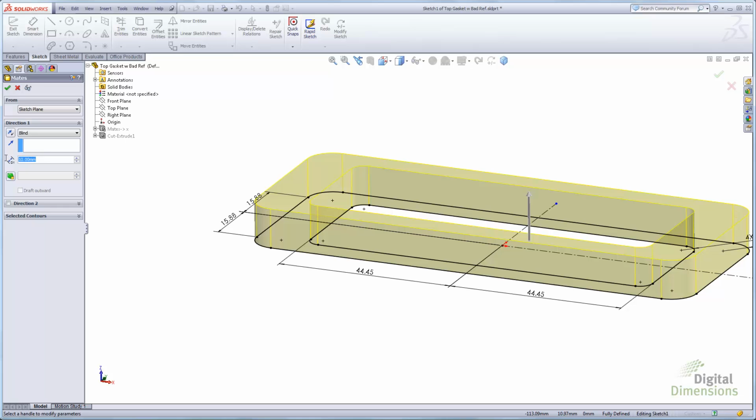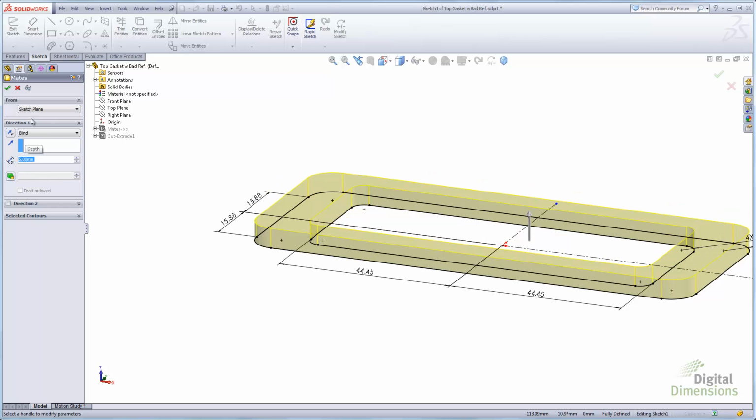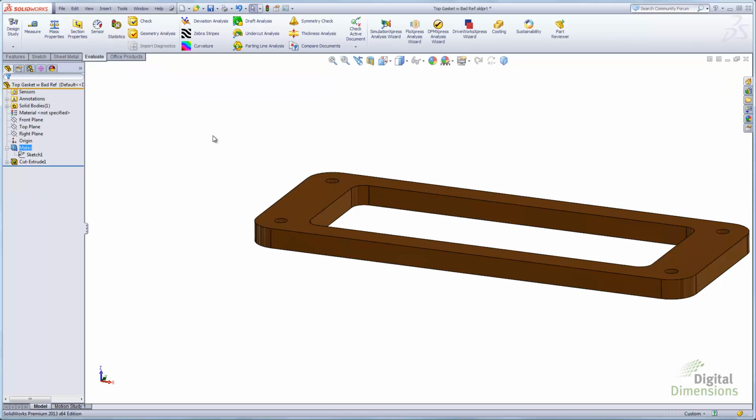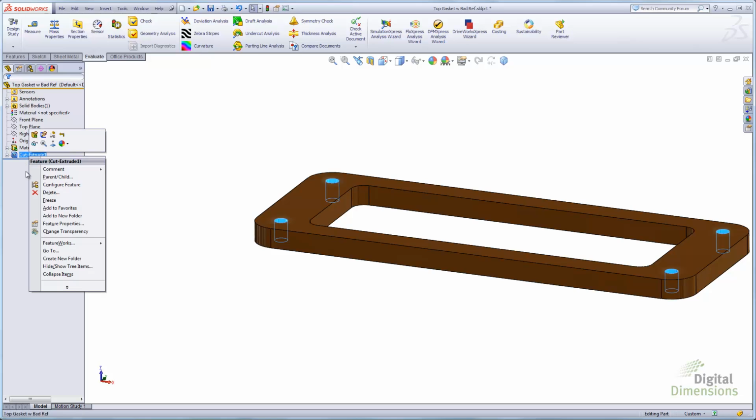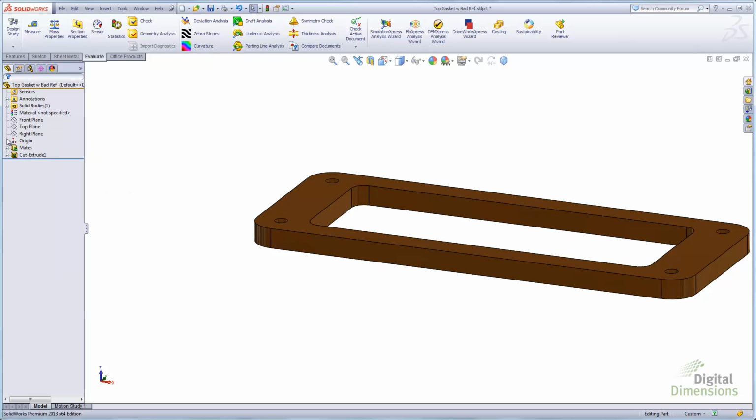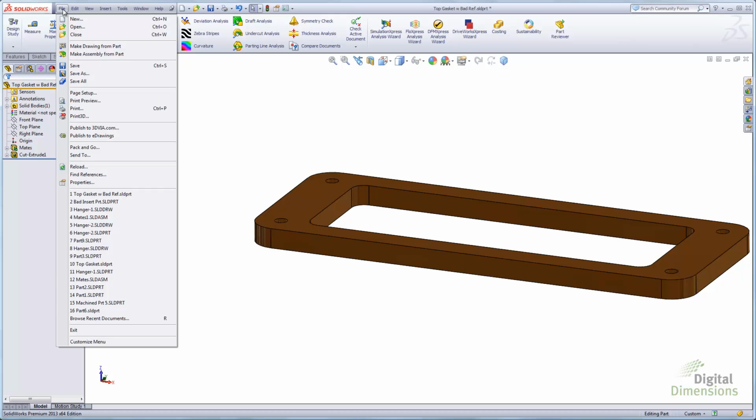So now I'm going to change it, because you can see it wants to make it 10 with the blind depth. I'm going to change it back to 5. And with that final step, the external reference is gone. How do I know? The list external reference button is gone for both of them, and they always double check.